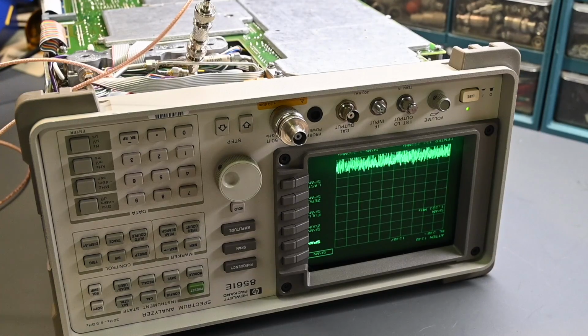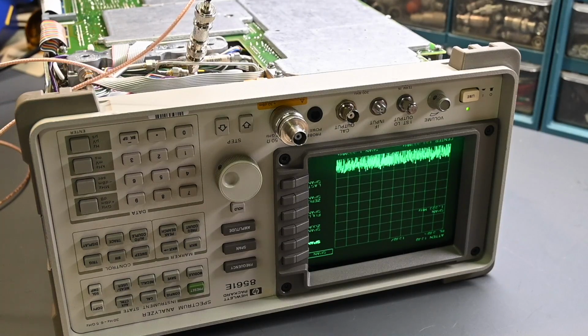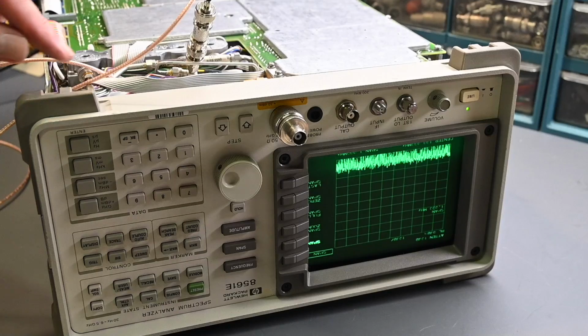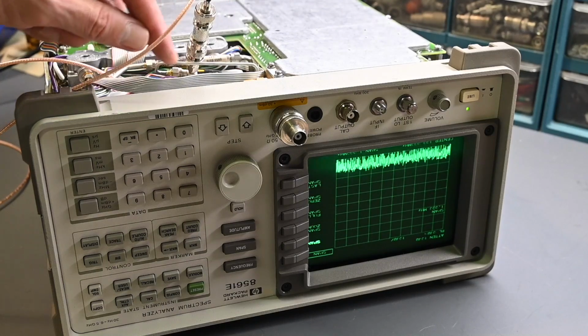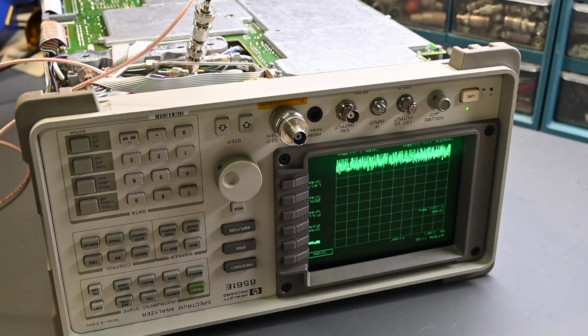And I have a DC block on the output of the signal generator. Absolutely don't want to have any DC voltage going into the spectrum analyzer. Be very costly, and damage and other problems would definitely occur. Now, there's no reason to think that any DC voltage would come out of that signal generator, but it's just a good practice to have, because at this point we're after the attenuator, which has that blocking capacitor in it. So this DC block is essentially just a capacitor that's in line with this coax. So just a good safety precaution.